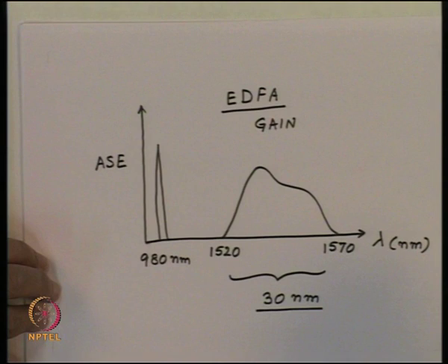Whereas when the signal is attenuated to a significantly low value, if you put an amplifier then, you get an amplification in the signal. So we will see later that as we are having a long length, we will put the amplifier at locations where the signal is attenuated to a low value, and then you get the appropriate amplification by putting the amplifier there. So this effect essentially is some kind of a saturation effect which is taking place inside the amplifier.